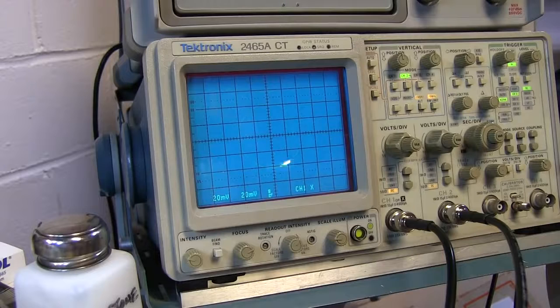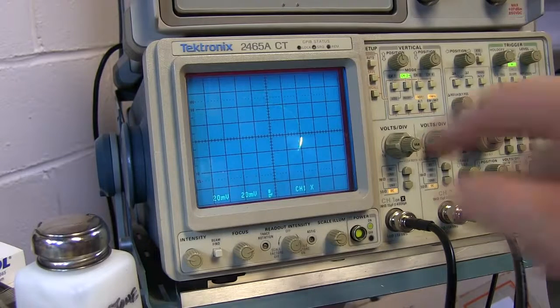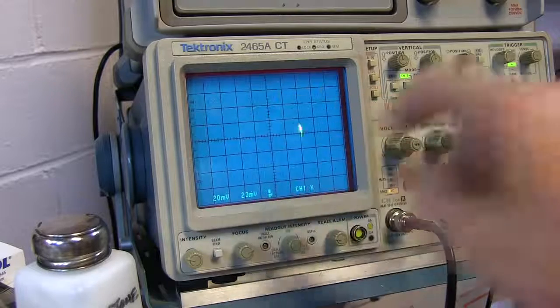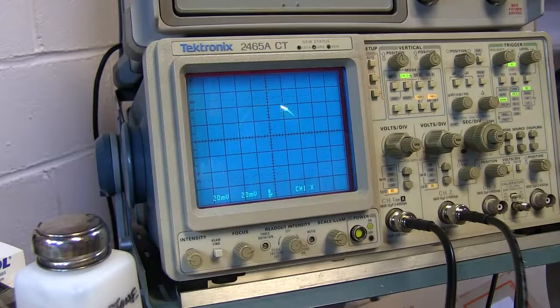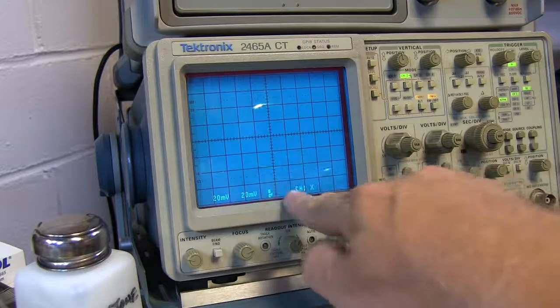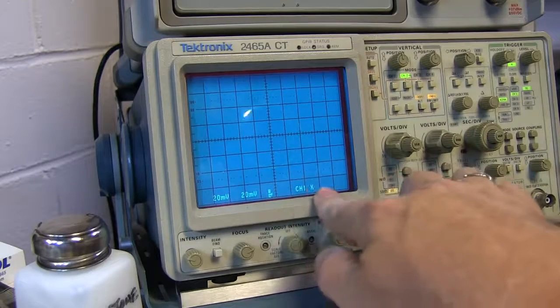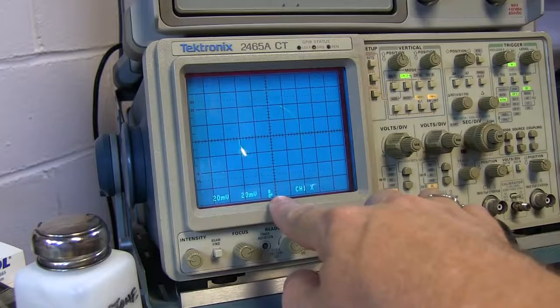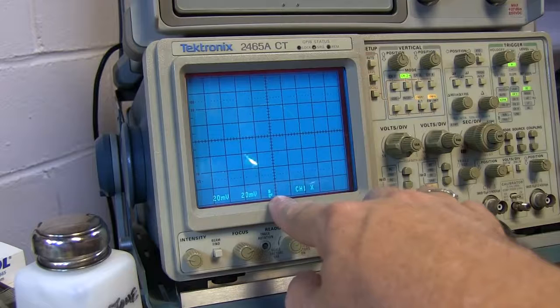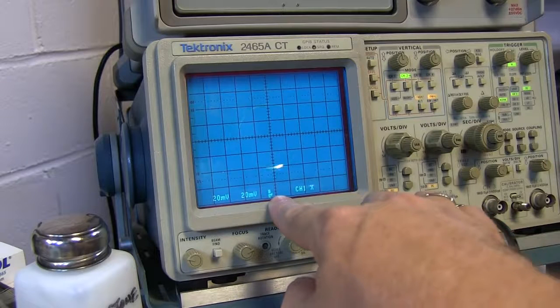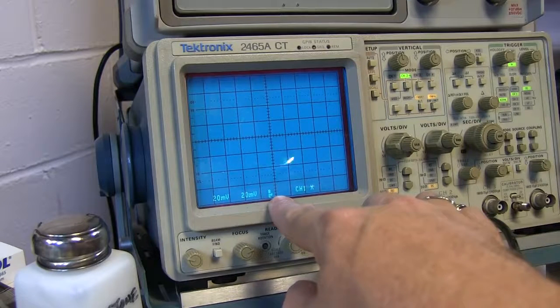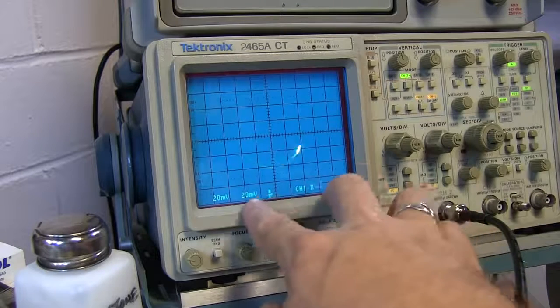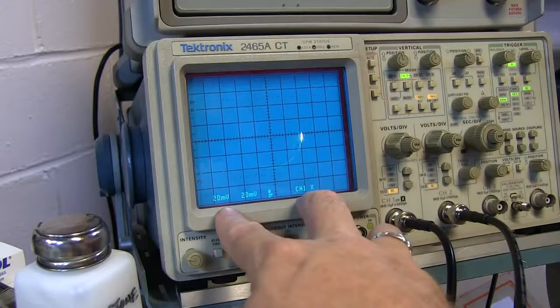So I'm back at the case here where I've just introduced a 1 hertz frequency offset. And so we're seeing essentially that vector spinning around at a 1 hertz rate. Now what that represents again is that the carrier frequency in this case, say, is above the local oscillators. Now if I simply invert one of the quadrature oscillators, basically introduce a 180-degree offset to it, I can essentially reverse which of those two signals is leading.